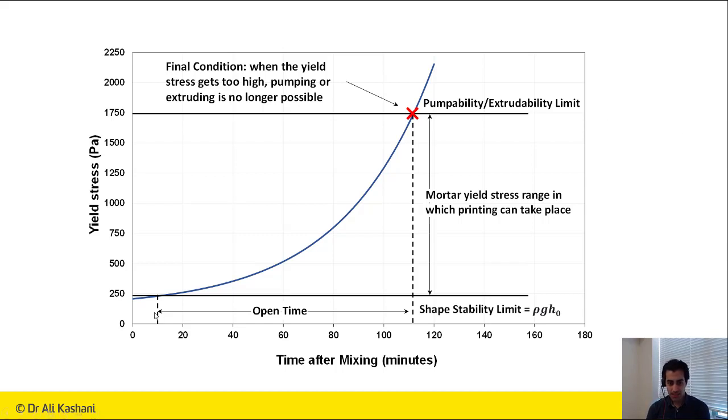The other thing is pumpability. There is a threshold based on the performance of the pump, the nozzle size, etc., and also the distance that you pump it. Above a certain yield stress, you cannot pump and extrude the material, which is another line, the extrudability limit. The time from the start until you reach that point, after which you cannot extrude the material anymore, is your open time. That's the time that you have for a batch to be printed.